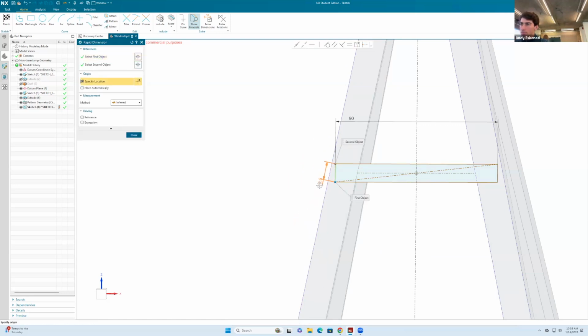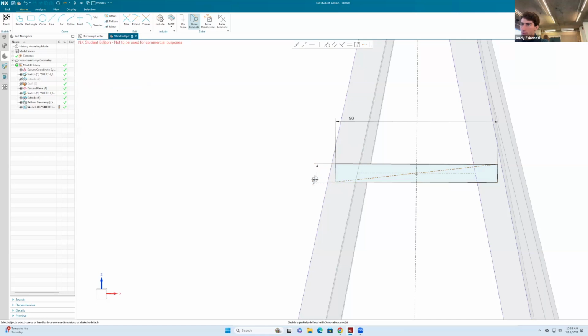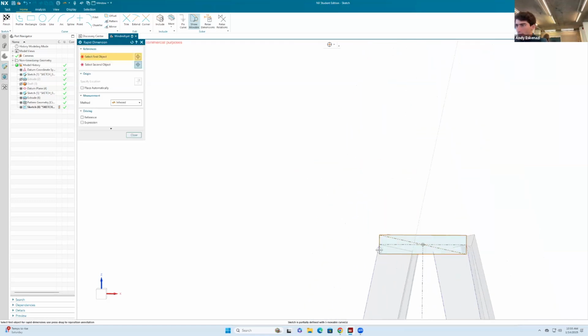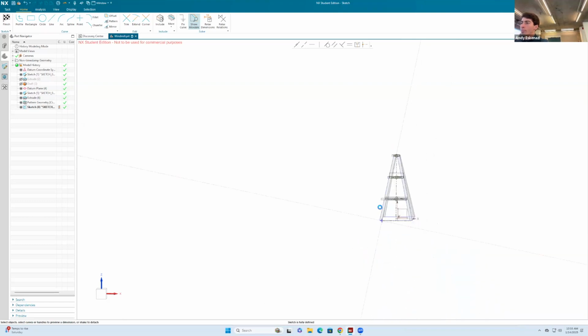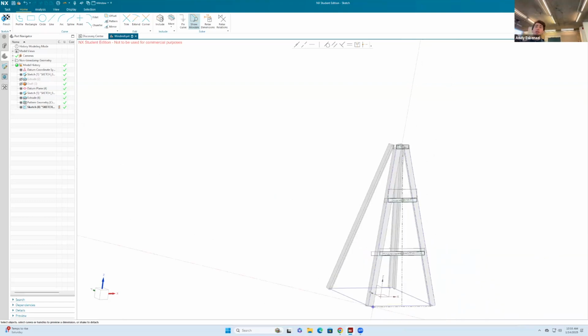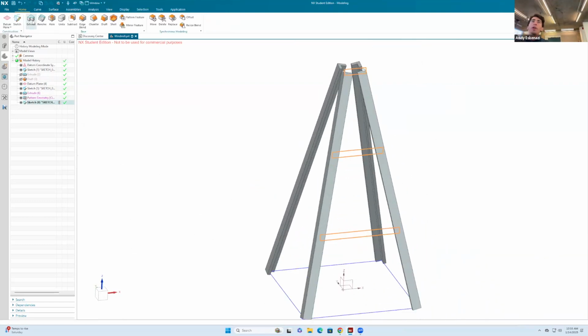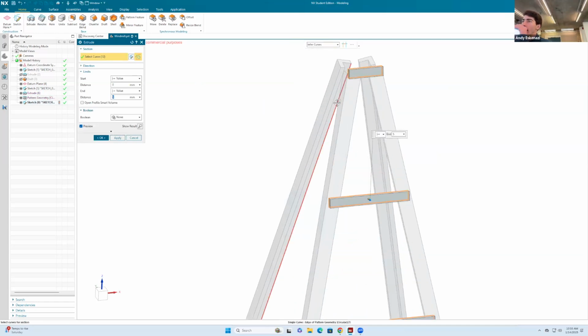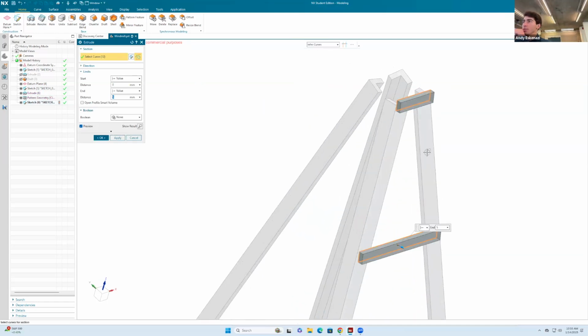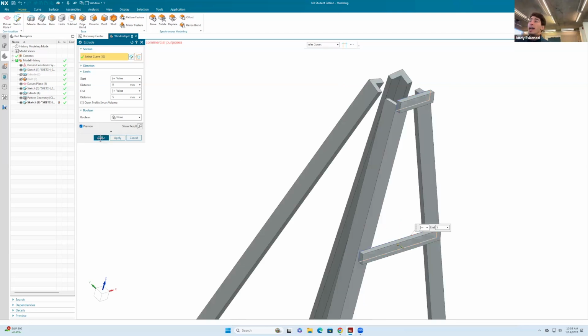Oh, let's make that 10. And let's make that 10 as well. Good. So now, very easily, we'll click on finish, and then we are gonna extrude these guys by 5 outwards. That way it's the same thickness as we had in there. And we also make it none.